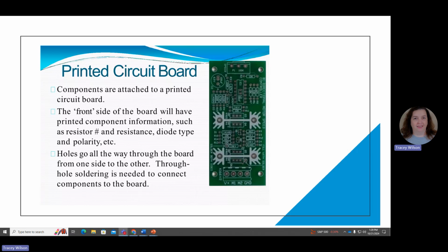If you connect two of them together incorrectly, or if you set them down on a metal conductive surface, you could short your whole board out if it's plugged in at the time. If the power's not running through it, not a problem because there's nothing to short. This is why I would say that you should always unplug the power source from your Arduino board while you're recabling and rewiring.